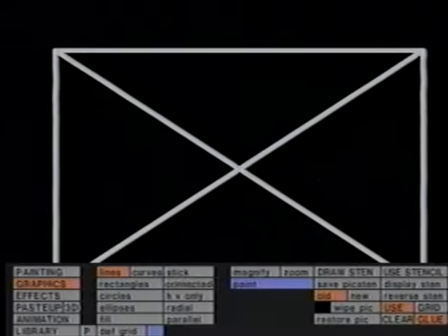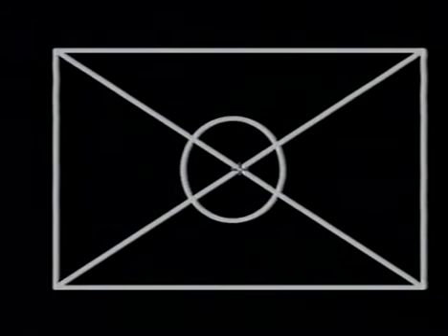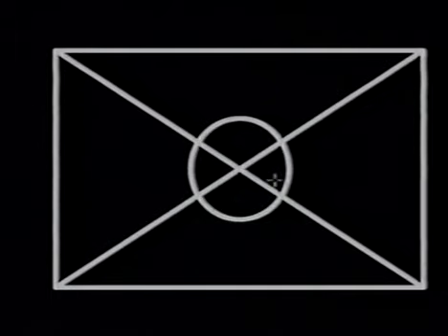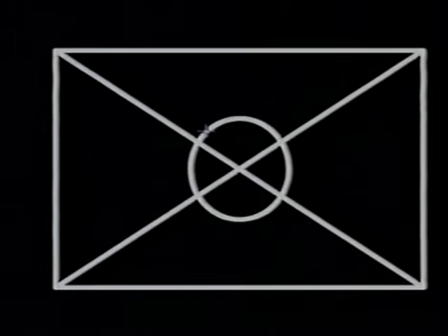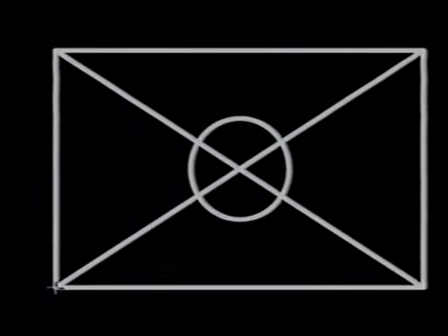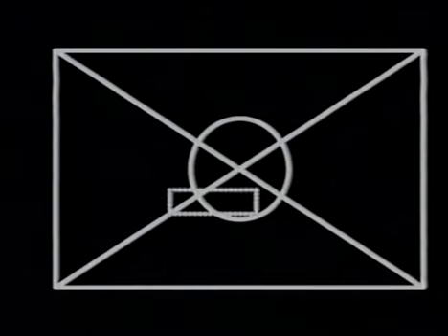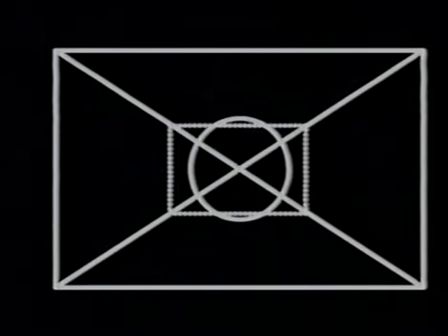The intersection of the lines creates a new glue point, which we can use as the center for a circle. Note that the circumference has glue. Picking up the glue at the end of a line, glue can be slid along. When at the required point on the line, removing pressure from the pen allows that point to be used as a new glue reference. In this example, to construct another rectangle.